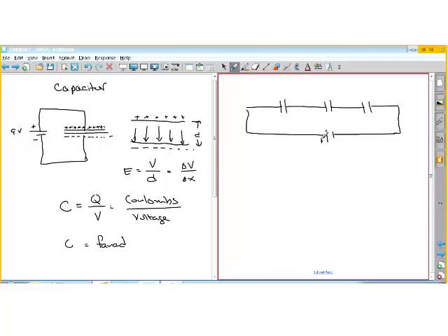So again, this is the positive pole, this is the negative pole, we'll call this 9 volts. If all these capacitors were the same, what you'd end up with is 9 volts here, 6 volts there, 6 volts there, 3 volts there, 3 volts there, 0 volts there, and then you would go from 0 to 9 across the battery, just because from symmetry you can kind of think about that.